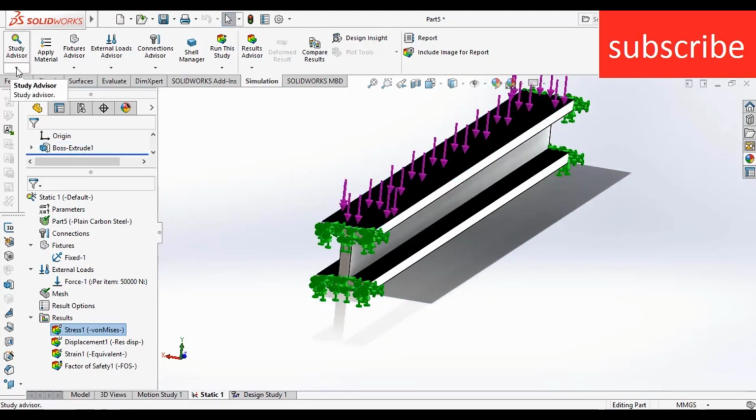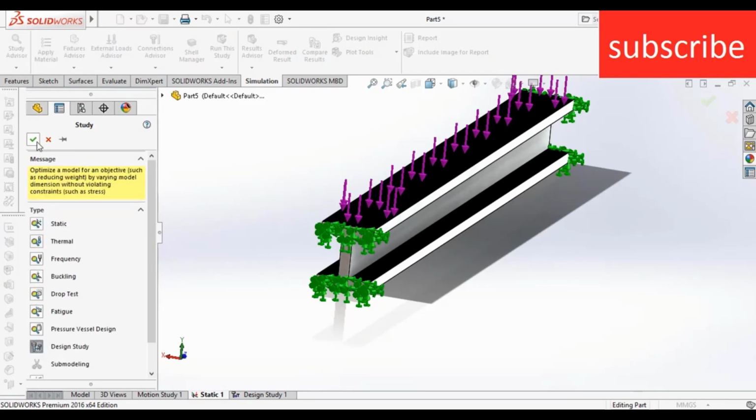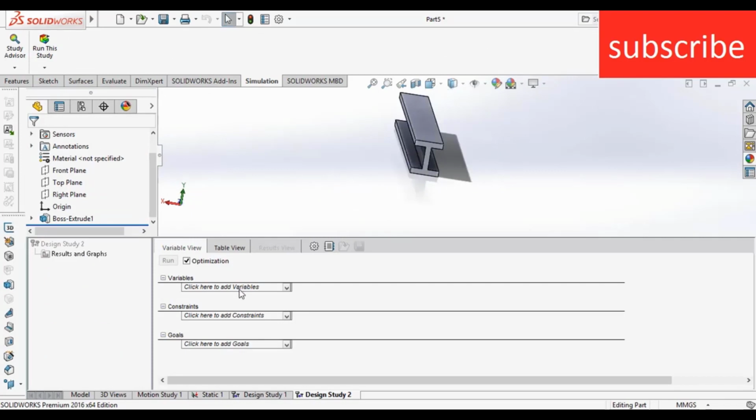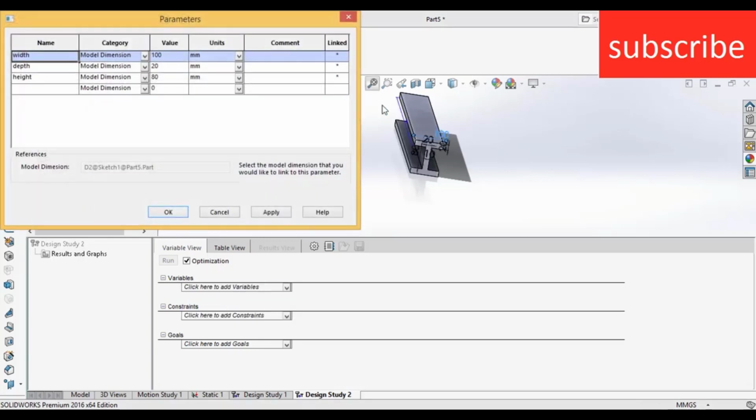So to do a design study, click on the study advisor arrow, click on new study. After that, select design study and click OK. Now here you see it is asking for variables. So a question arises in your mind, what is a variable? Click on add parameters.